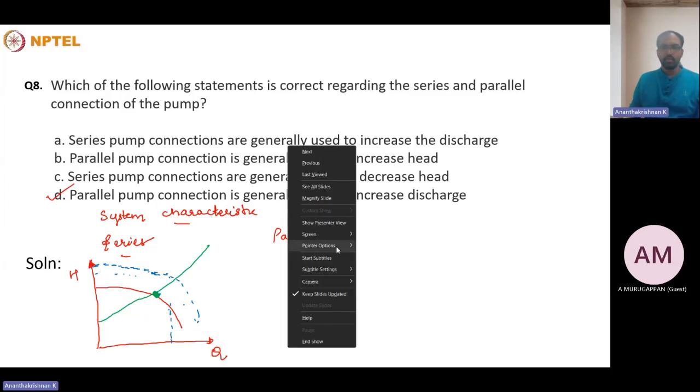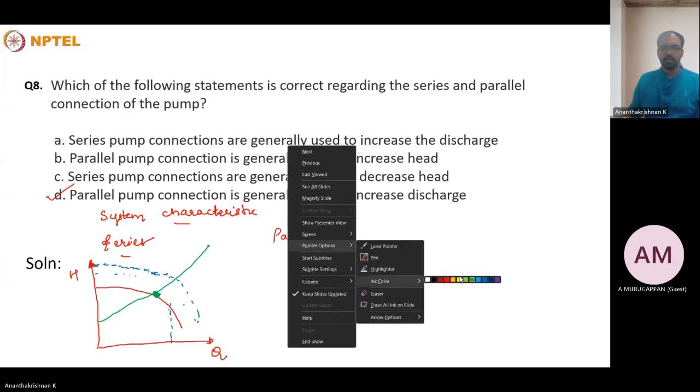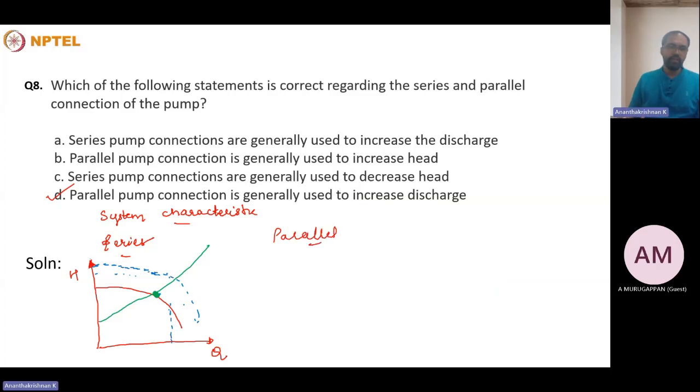That was a mistake. When we increase the number of fittings, the system characteristic actually varies. The system characteristic might vary like this. In that particular case, we will achieve a higher head by including a lot of pumps in the same system at almost the same discharge.